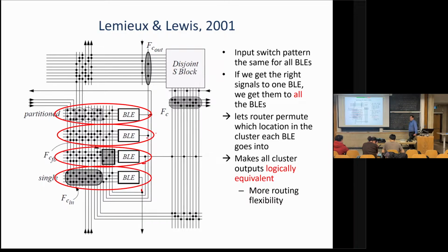And then in addition to that, you would also get the benefit that when you do that swap, you would change timing. You swap maybe the fast and the slow pins. You're going to have to show this to me afterwards, because I think this is too complicated for me to absorb here. This exact pattern sort of decouples the decision of how do I route to the input of the LUT